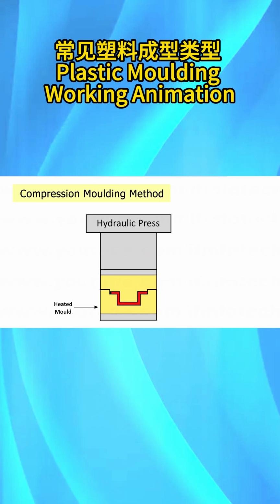Then plastic material is forced under compression to flow rapidly around the cavity. The heat from platen causes the plastic to cure, resulting in permanent change in shape. Here the component is ejected from the mold and excess material formed at edges is removed. Thermosetting plastic material is used in compression molding.